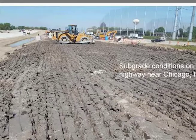Okay, so this is an example project. This happened to be on an Illinois DOT project. They're placing subgrade, and it's fat clay subgrade, variable moisture content. A lot of variability, coefficient of variability upwards of 100%.